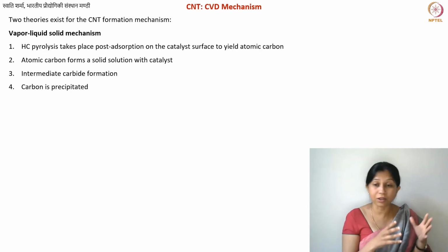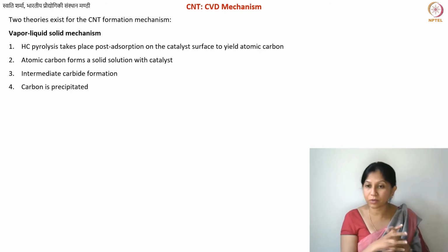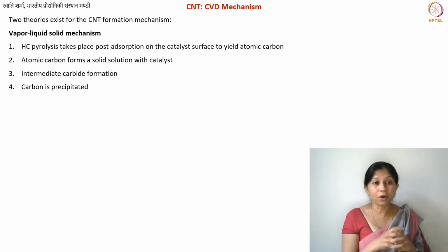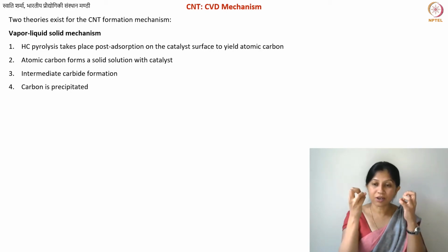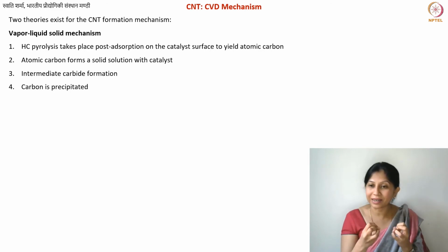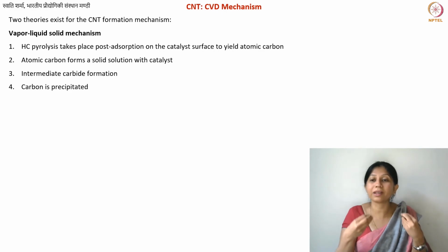metals, also in the graphene CVD lecture, and at some point when I was talking about the pyrolysis of methane. So you know that carbon solubility becomes very, very important. In different metals, you have different solubility and different solubility curves, and accordingly, you collect your carbon at different temperatures and so on. Okay. So the idea is that the carbon atoms, the atomic species, go inside your catalyst, and then there is a carbide formation, and then from that carbide the carbon precipitates out.